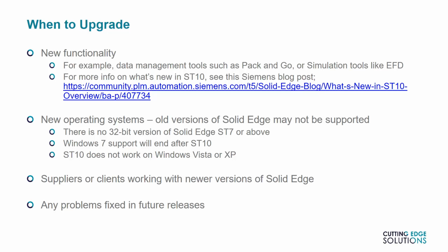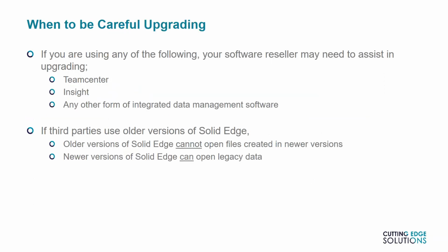With all that in mind, there may be very good reasons to not upgrade Solid Edge, at least not on your own. Some of our customers use PLM or PDM software such as Teamcenter, Insight, or any other integrated data management solution. If this is the case, upgrading Solid Edge with a normal install procedure can cause these integrations to fail, and we would strongly recommend contacting your reseller for assistance with upgrading in this case.